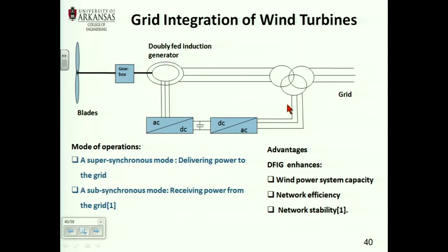Basically what you do is, you have here a transformer, which has 3 windings, right? One to go as before, and a third winding, where basically the rotor is. So now, instead of having a squirrel cage on the rotor of the induction generator, you have a wound rotor. You go to a more expensive machine.